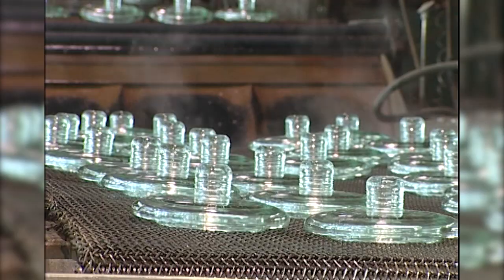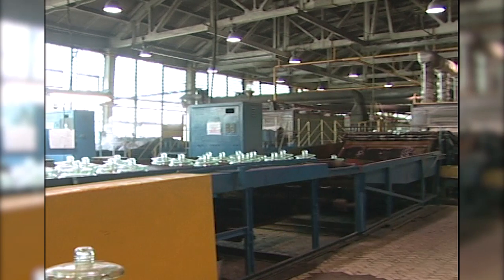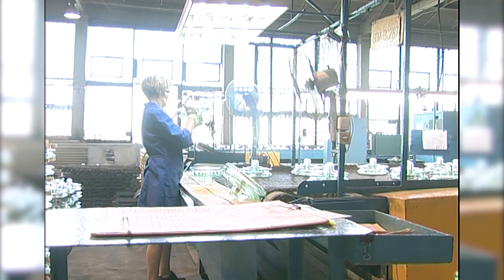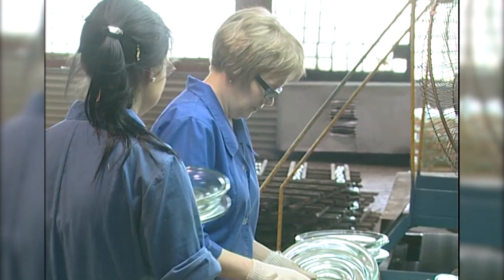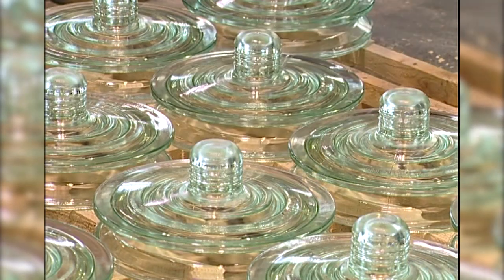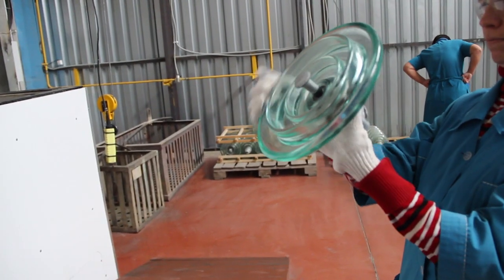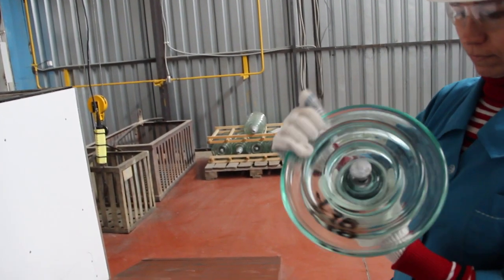After it, the glass is not processed in order to avoid defects. Toughened glass parts should meet the special requirements. Major defects like bubbles, holes, foreign inclusions are unacceptable. Part screening based on inner inclusions is performed at the production site, since the properties of glass allow making it easily. It is necessary to select glass insulator manufacturers with the high level of quality inspection and technical process.